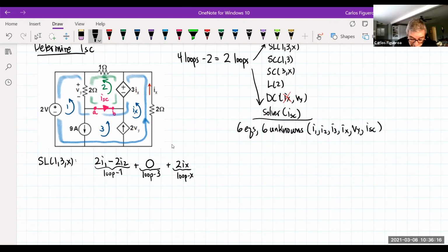So now, let's make sure that I have that right. And so now I'm going to look at my sources. So here I go. I started over here with the resistor that's labeled VY. So if I go around, typically I put my equal sign further out. So here I go, a constant source, I hit a plus, I take it to the other side. So I got -2. I'm coming all the way around. Look at this, I hit the positive 3IX, but because that's a voltage source that's dependent, I want to keep it on this side. So I write 3IX. And then I keep going all the way around, I'm done.